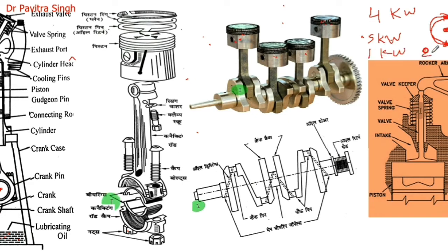And 0.25 kilowatt went out in the exhaust. Clear? So we have to subtract these from 4. We have to deduct 0.5, 0.25 and 1 kilowatt. So the remaining part will be our shaft work, shaft power. So we get power in one stroke out of these 4 strokes.